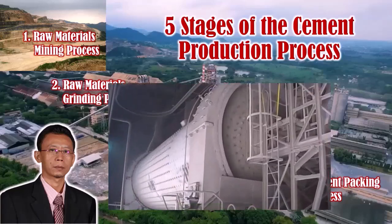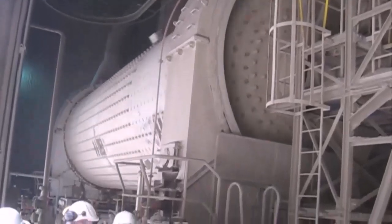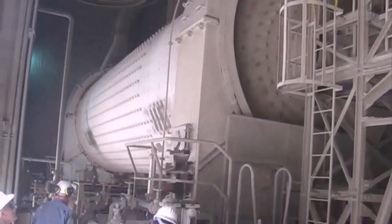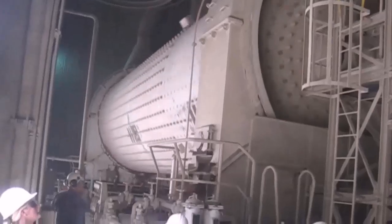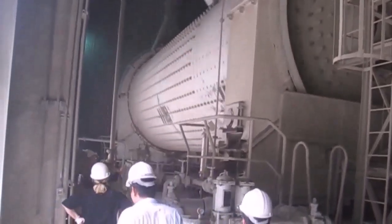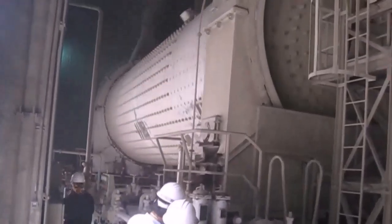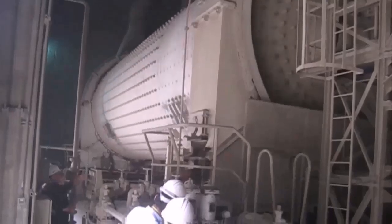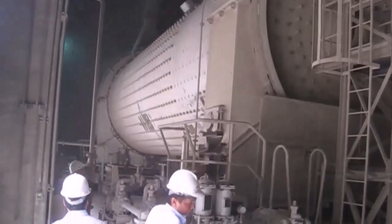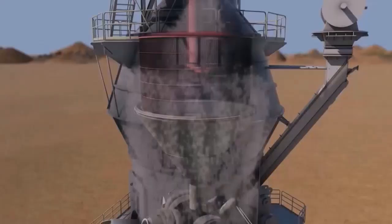Four, finished cement grinding process. The clinker is mixed with other additives and gypsum, with a predetermined mixture composition fed into the grinding machine simultaneously. Cement quality is strictly controlled to meet quality standards for the type of cement being produced. Cement grinding machines can use ball mills or vertical roller mills.